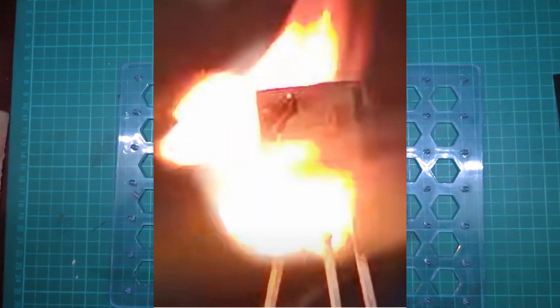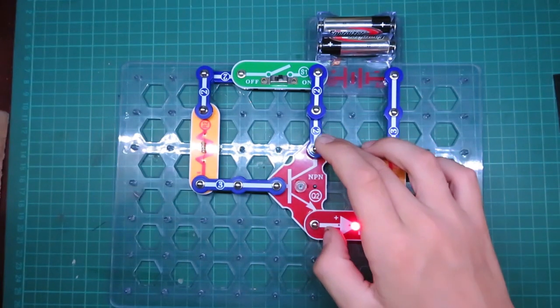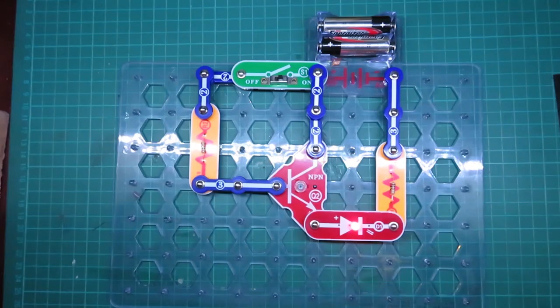So another way you can also burn out your transistor is exceeding the voltage limit between the collector and the emitter, also exceeding the current limit between the collector and the emitter. That's a few ways you can burn out your transistor. It might not physically burn, it might just cook itself inside, but yeah, you don't want to do that.